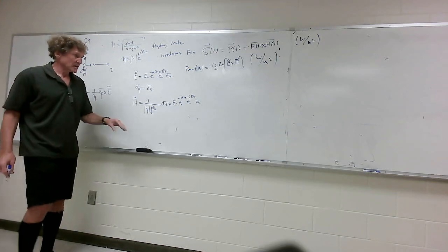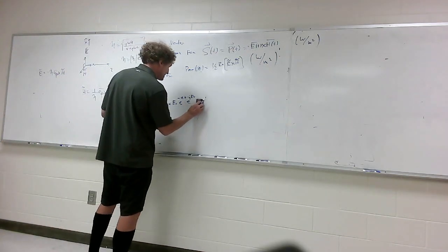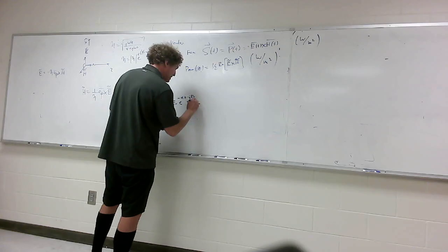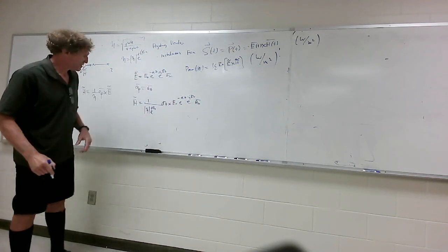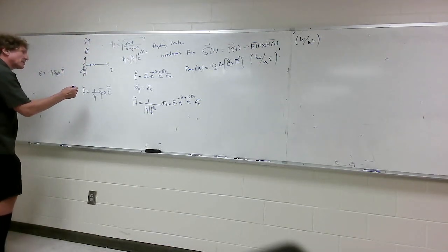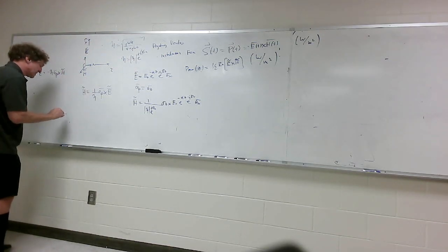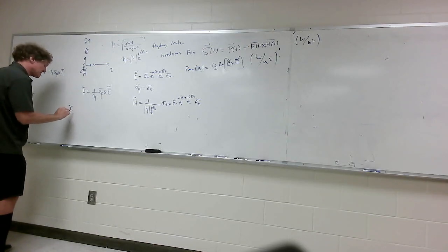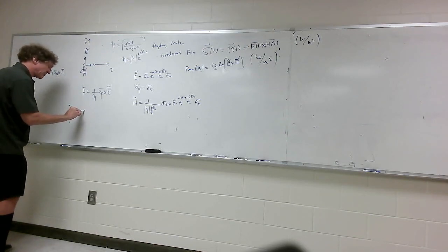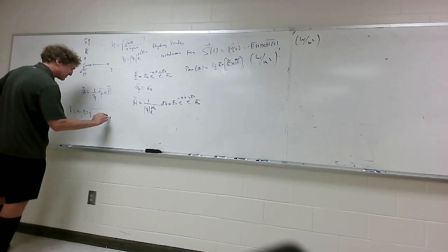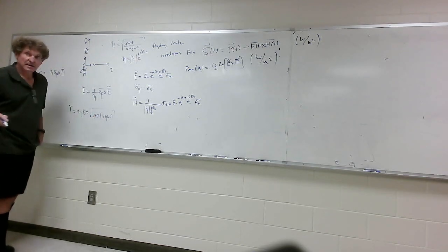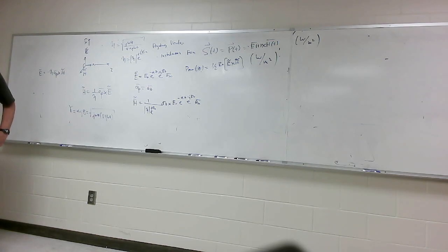All right, maybe I need to blow this up a little. And this is because sigma's 0, right? Are we still assuming? No, sigma's not 0. This is a general form. Sigma, matter of fact, we're assuming this could be complex, so sigma is not 0. And so gamma is equal to alpha plus j beta is equal to the square root of j omega mu times sigma plus j omega epsilon. You all with me? You have to make sure you know these things very well. I mean, we use them all the time.